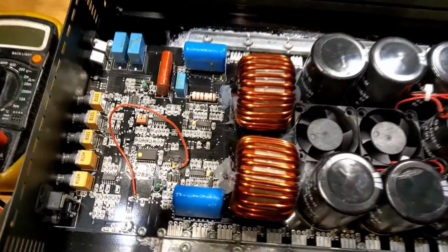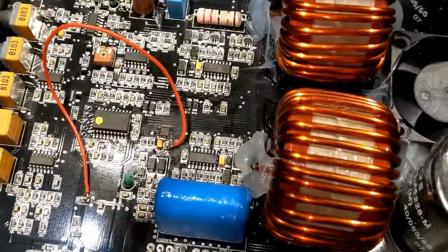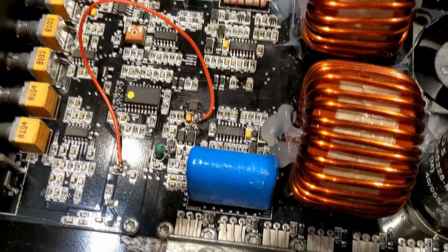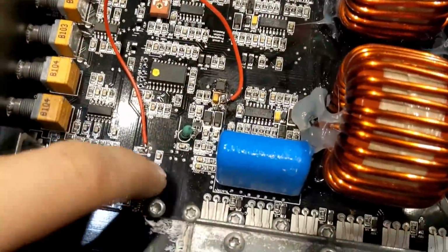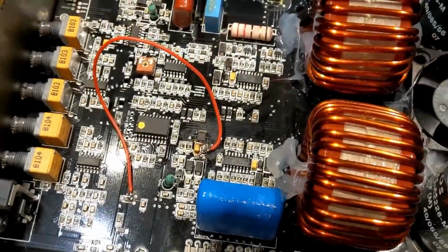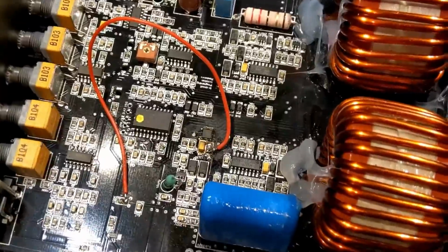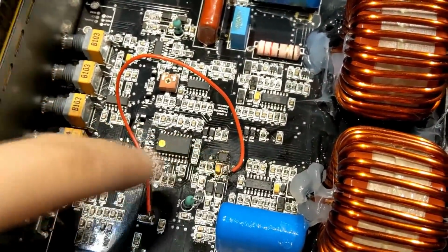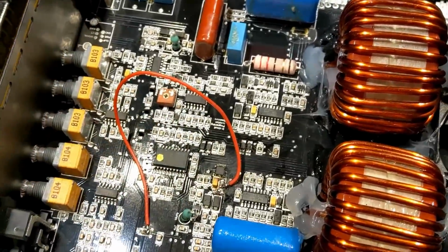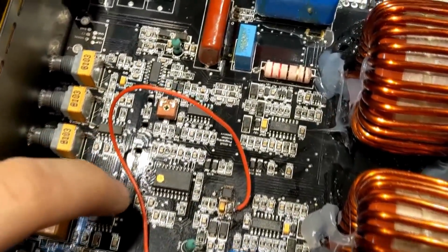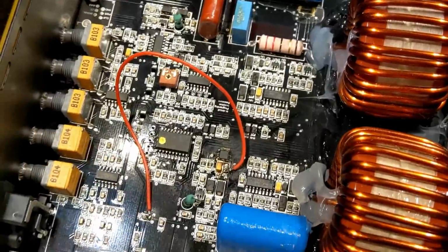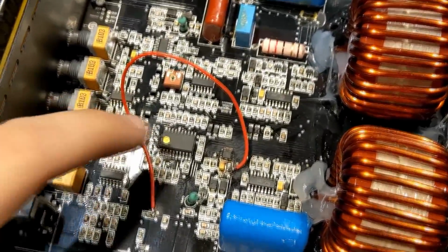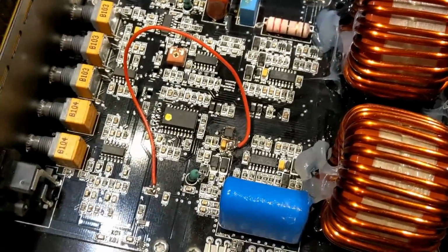So yeah, really strange fault, and still can't see where the blown trace is. It'll be so small. It could be inside the layers. This could be like a triple layer PCB or something. But yeah, that works absolutely fine. So what I'll do is I'll tidy this up and make a shorter run, either from here or I'll find somewhere else at battery voltage. I think battery voltage also comes from over here near where the PRC is, because it registers battery voltage. And yeah, then that will be good to go.